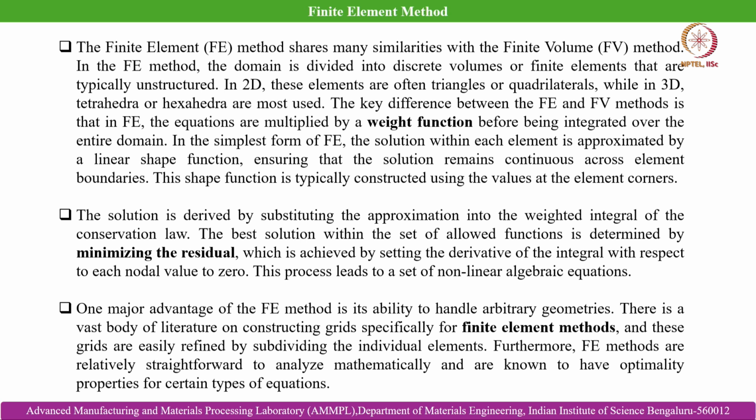One major advantage of the finite element technique is its ability to handle arbitrary geometries. There is a vast body of literature on constructing grids for finite element. But the one thing I would like to highlight here is that in case of solid mechanics problems, we generally go for finite element techniques, because it can be very efficient with unstructured grids also.